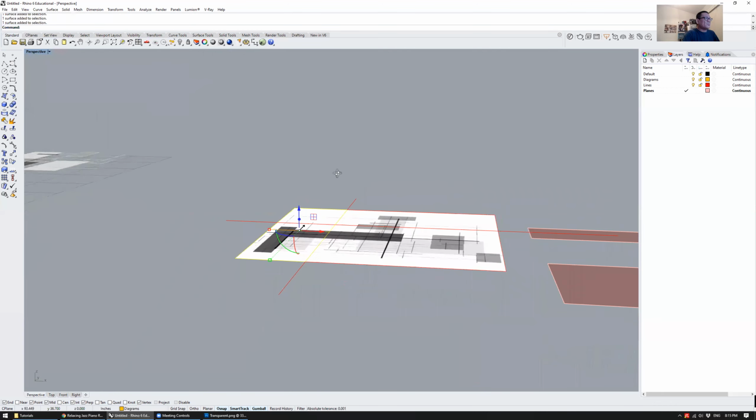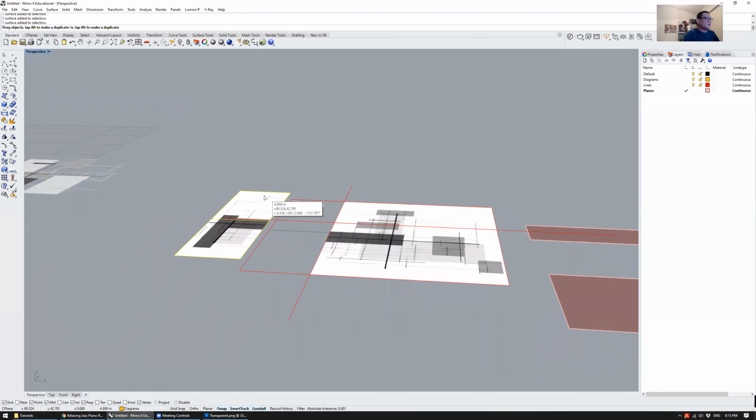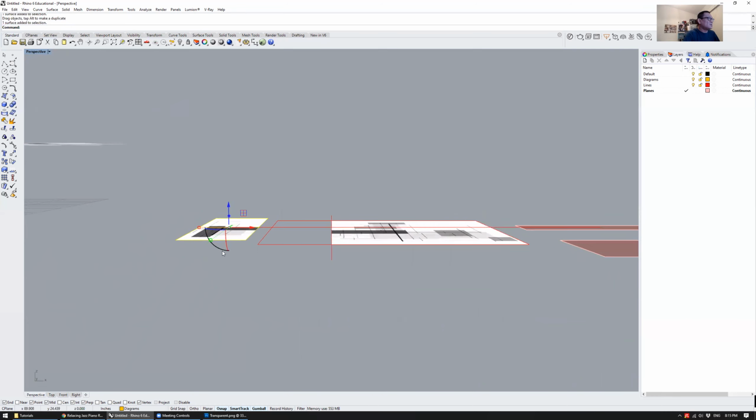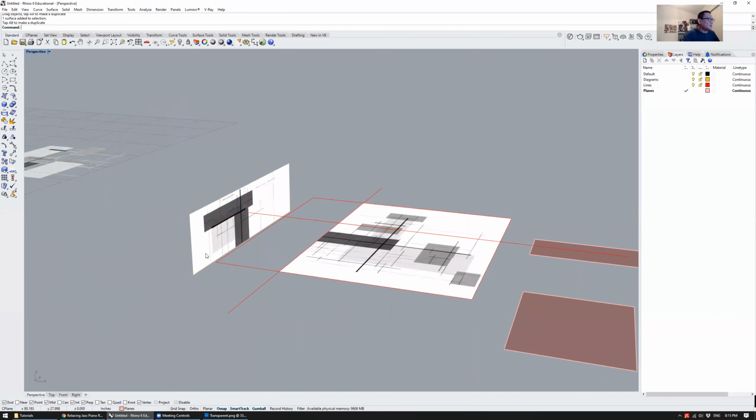What's cool about this is that I can now, for example, do a fold, and turn this 90 degrees that way. Then I'm going to use my move command, point to move from. Now, one thing you have to check when doing the move command with points is your Osnap, down here on the lower left, where there are some object snap toggles.